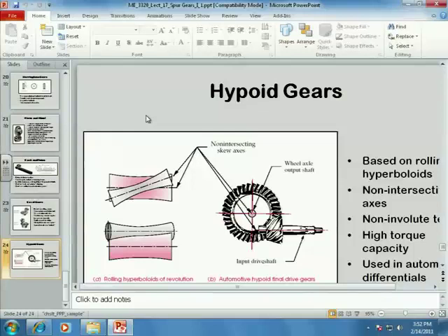Oh, by the way, rule of thumb is gear sets are, it's recommended you have no more than a 10 to 1 ratio between them. This is not worms, but regular two-round gears. Only because the minimum number of teeth is, what do we say, 16? That's 160 teeth to get 10 to 1. It's not to get big. So your packaging goes in the wrong direction.